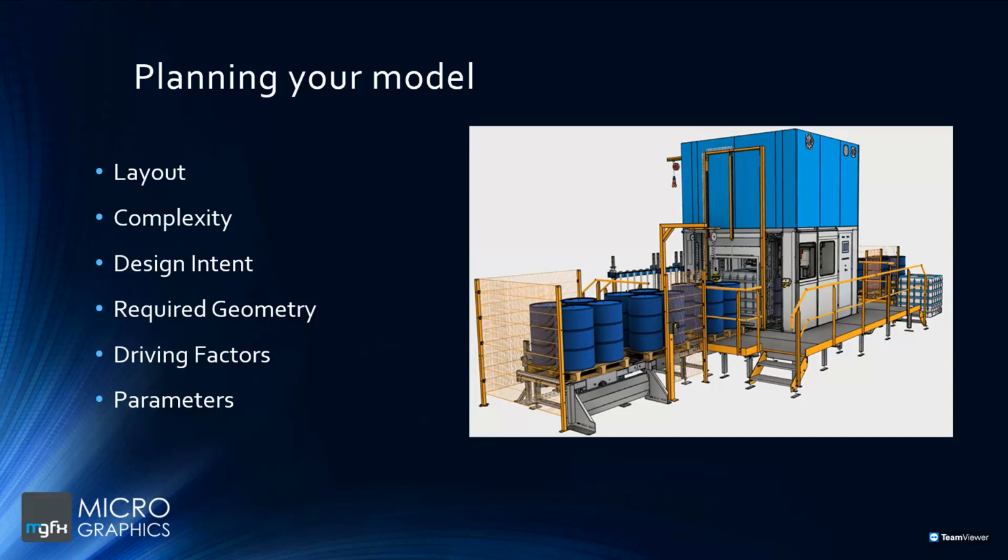So what you want to do is pre-plan the layout of your reference part, and this helps you understand the complexity of the task at hand. Firstly, you're understanding your design in its whole. You're not just starting with little bits and pieces of it and trying to piece them together as you go. At the same time, you can hash out your design intent. Your design intent is where you make decisions on what is driving the model creation, what is driving the geometry of this design.